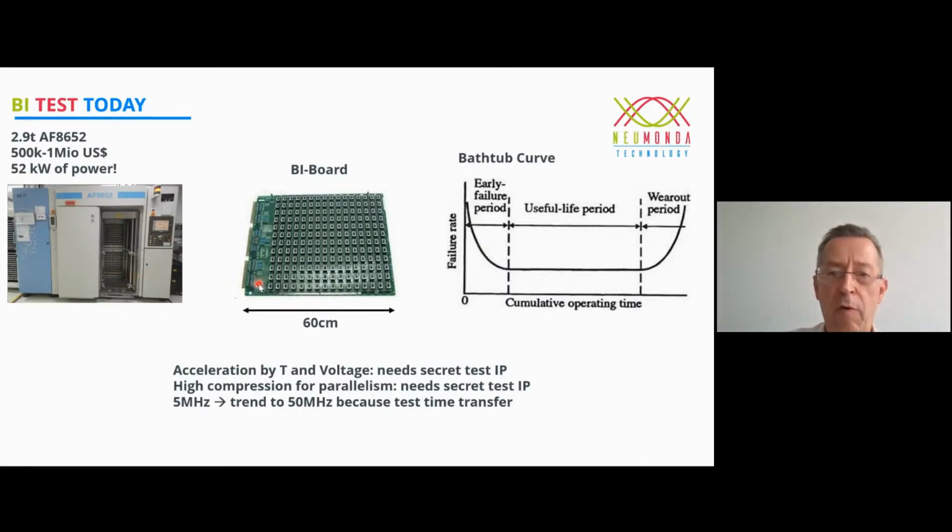The purpose of burn-in testing is to age the parts. So you want to catch infant mortality issues. You try to simulate the first 3 to 6 months of customer life of your DRAM component to find infant fails. Then typically, if you have done the burn-in procedure properly, you have stable fail performance over the lifetime of your semiconductor, typically 10 years.